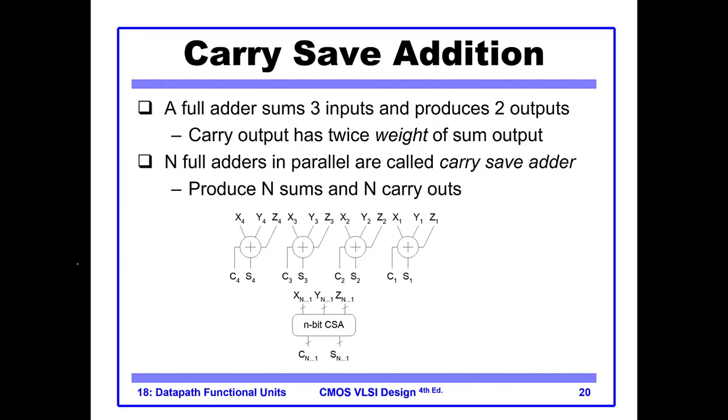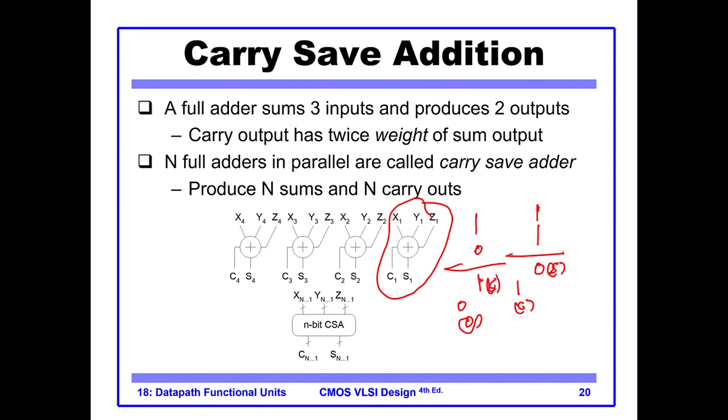One approach is called carry save addition, in which if you add 2 numbers, so let me add 1 1, the result will be 2. So I write it like this: 0 and 1. So 0 is the sum bit and 1 is the carry bit. If I do 1 0, the result will be 1 0. So this is sum bit, this is carry bit. So a carry save adder has 3 inputs and it has 2 outputs. Sometimes this is called a 3 to 2 compressor.